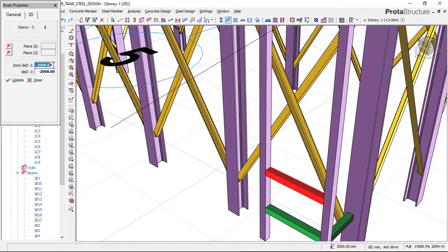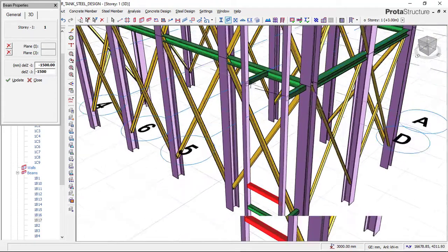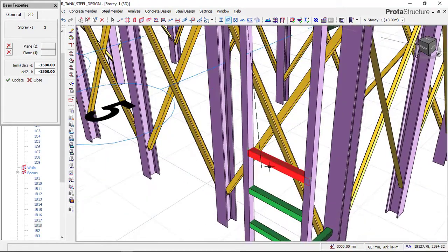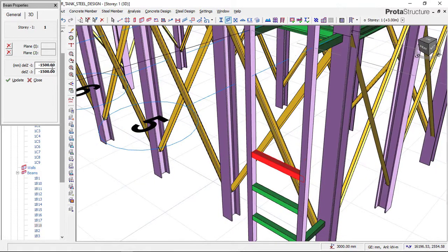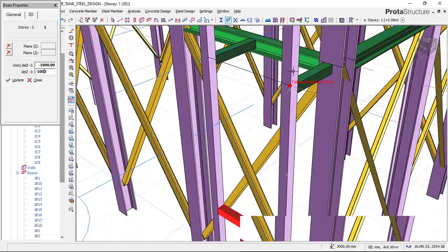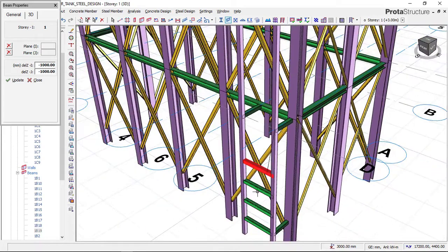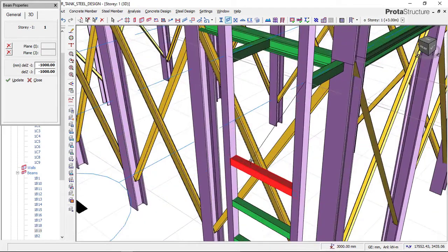So we go back again, minus 500 from here. We have minus 1500 millimeter and minus 1500 millimeter. And then we click again. You can now see again what we have. Again, the third one, we get again minus 500 there. We have 1000 millimeter. Again, 1000 millimeter. Okay, then we'll click again at these same spots. That's why I say this becomes our origin on how we will create all other risers.